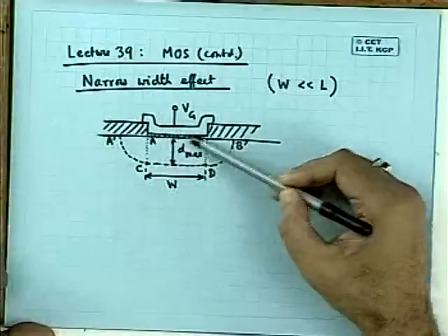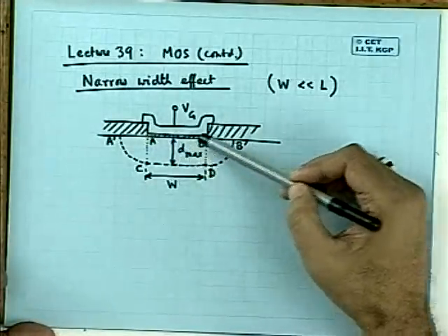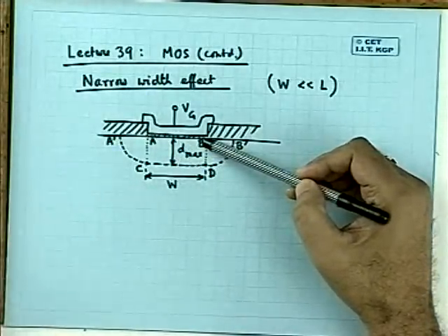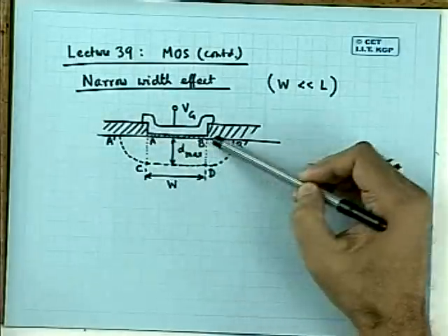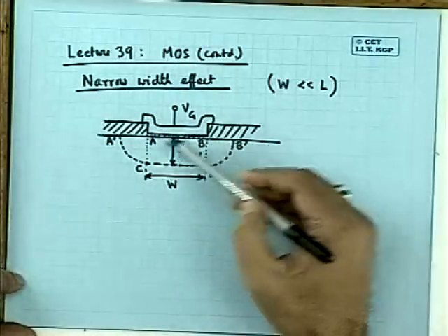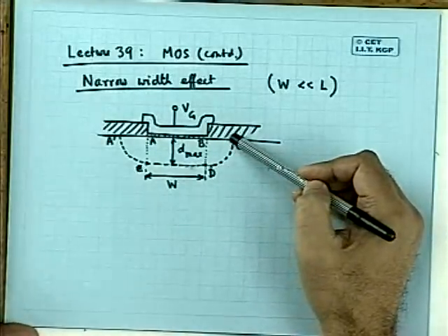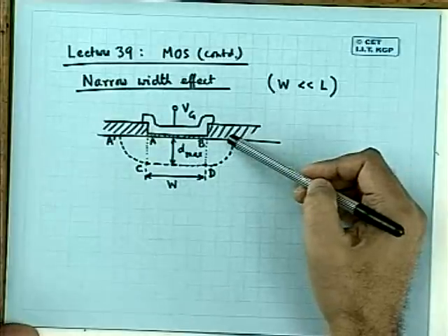It is confined, firstly, by a thin gate oxide that defines the channel along the width, and the remaining thick oxide. And what else is done to define the channel? A channel implant. There is a field implant also. In the remaining region below the thick oxide, there is a separate implant that is called field implant. Do you know why this field implant is necessary?